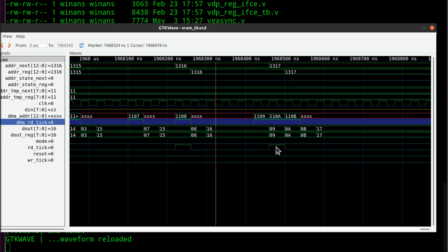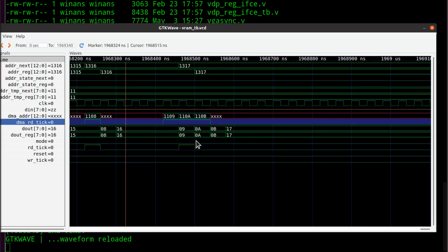And then we see over here, we have a bunch of DMAs with a read in the middle of 3 DMAs in a row, and this was done for the purposes of making sure the address counter does in fact advance if you end up with an access pattern like this where the FSM reads 3 in a row and the CPU consumes, as we'll see later on, the 16 that came out here and is stored in that cache register.